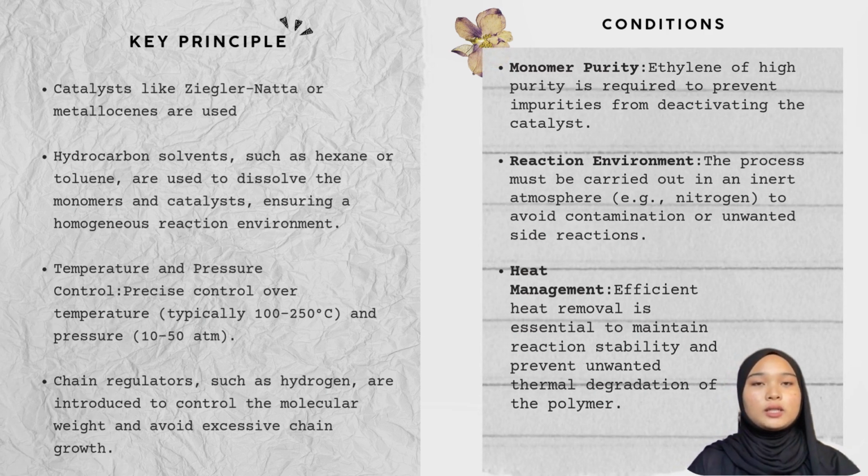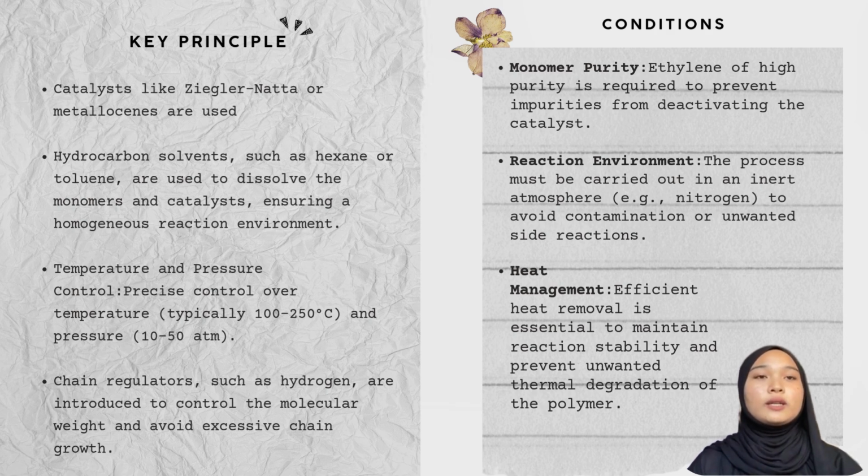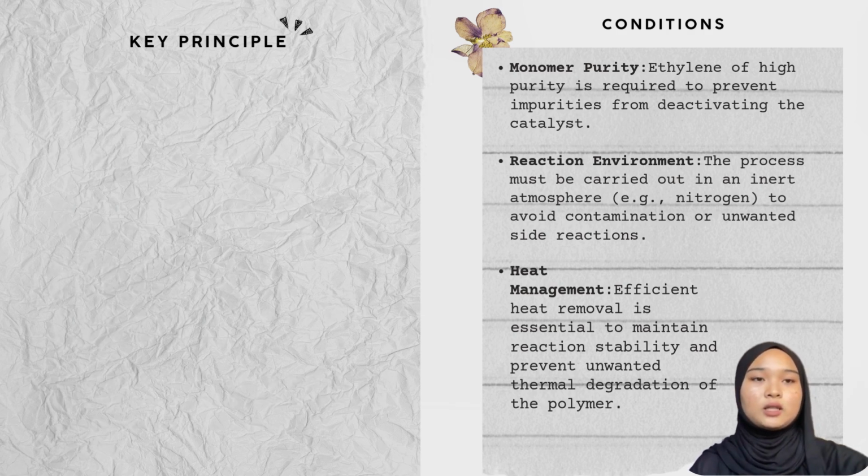As for the conditions, monomer purity is crucial to avoid catalyst deactivation. The second one is an inert atmosphere like nitrogen is required to prevent contamination. The third one is effective heat management, which ensures stability and prevents polymer degradation during the reaction.